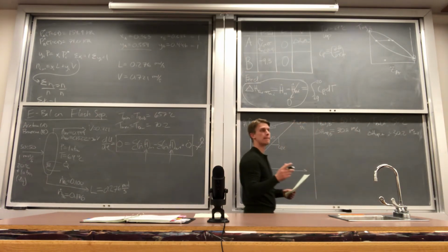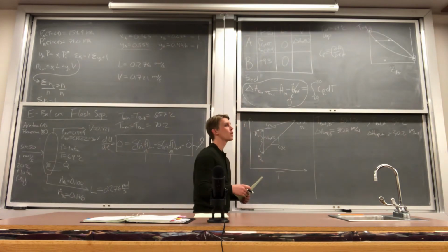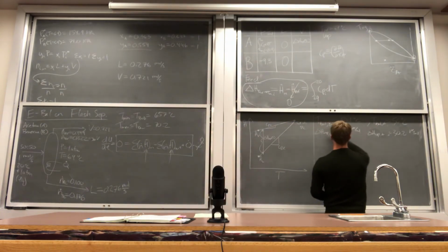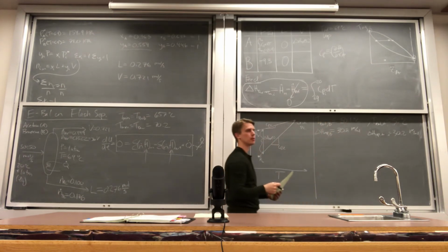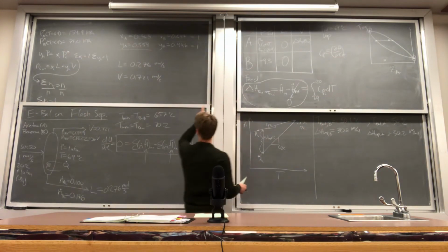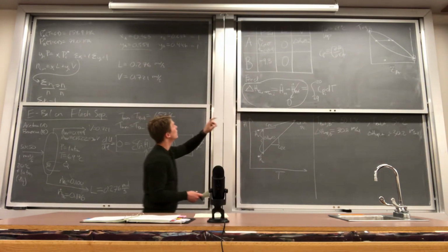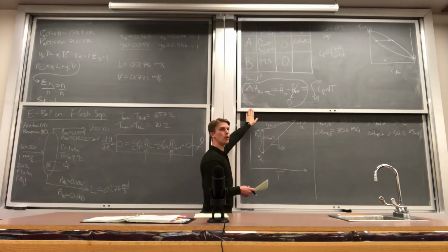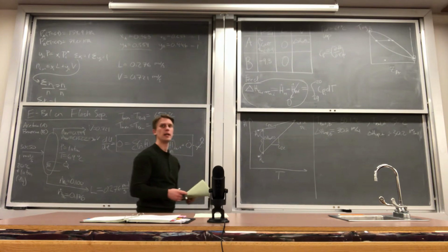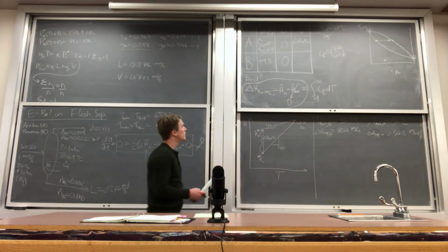So those are all at 1 atmosphere, right? The normal boiling point here is at 1 atmosphere pressure. Now we could be operating this flash separator at a totally different temperature and pressure as well. We could elevate the pressure significantly higher to get this thing closer to its critical point, and it would change our calculations quite a bit.